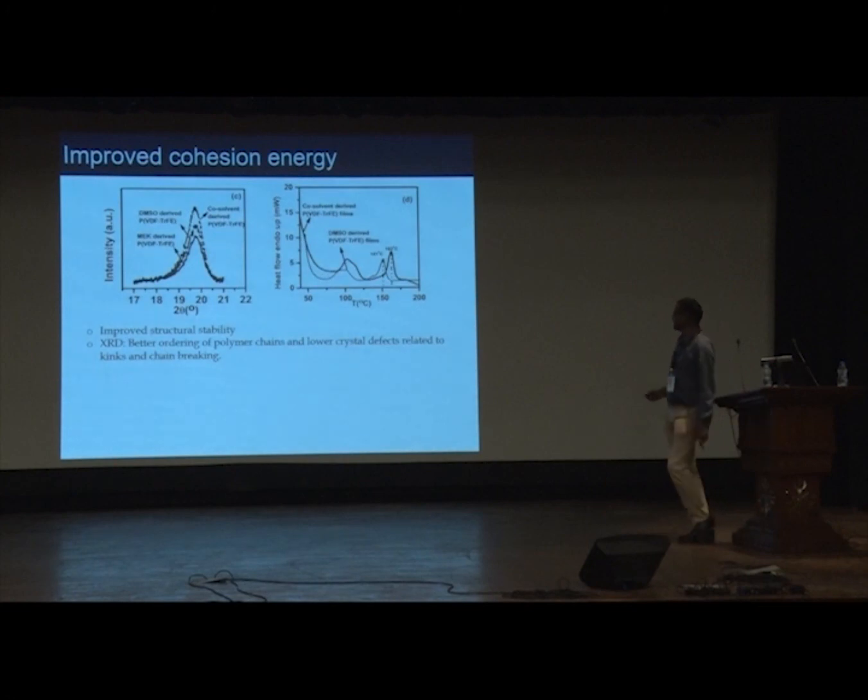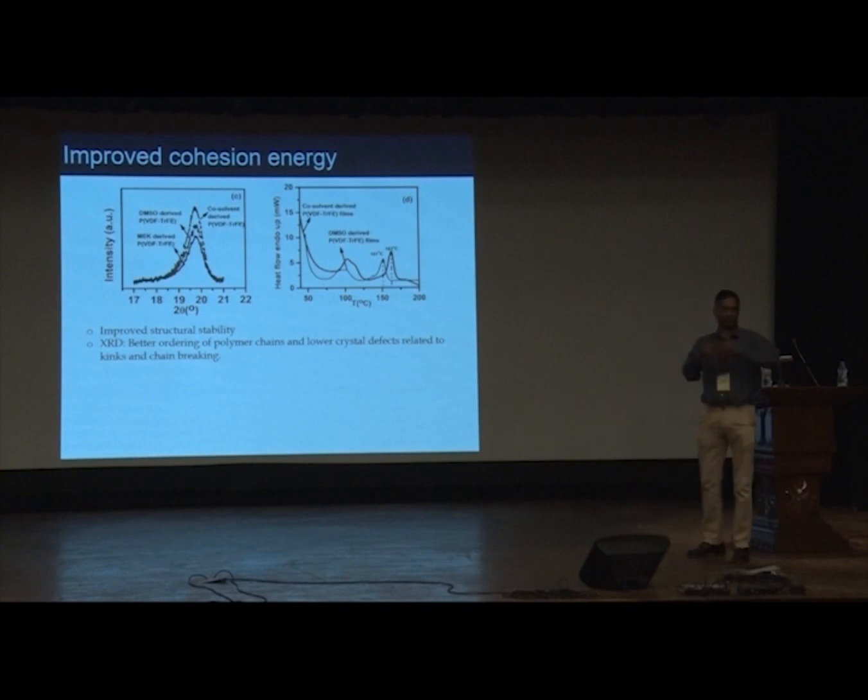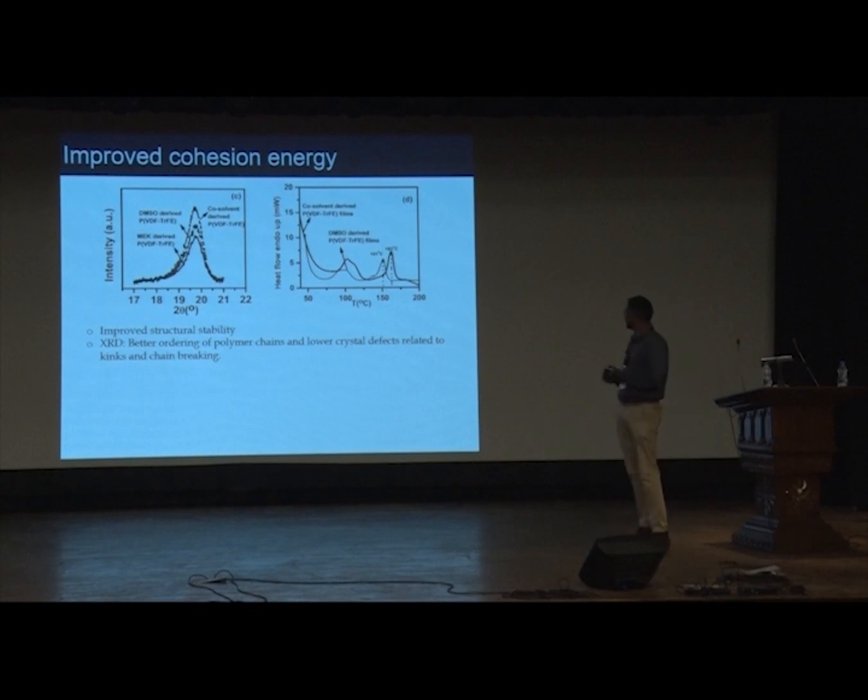What we found, interestingly, was that the X-ray diffraction pattern showed that the films which were co-solvent derived had better crystallinity. And we did some DFT calculations as well, whose result I'm not showing you here. They all suggested that there is a better cohesion of chains, and as a result there is better chemical stability in the chains, leading to very good fatigue performance.